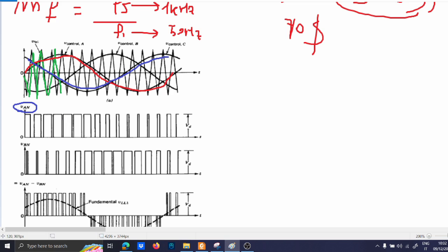And this is like this. So, as the sine value increases, the duty cycle increases as well. If the sine value is low, the duty cycle is smaller, as you expect. As you can see here, you have the minimum point of the sine wave, and you have a very, very low duty cycle.